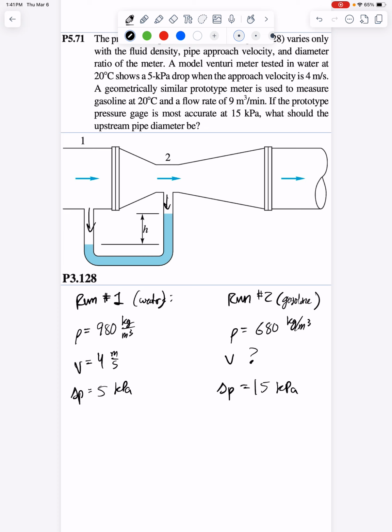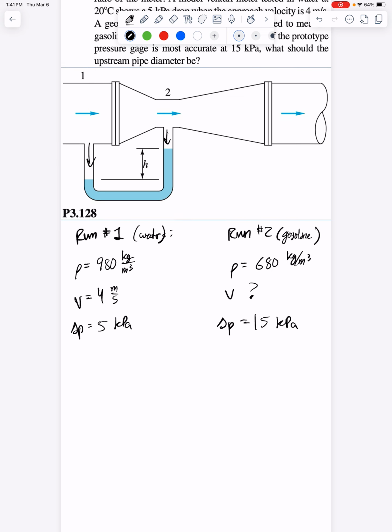First up, we want to match the flow characteristics between both cases in order to obtain this v value, because we want to make sure that the velocity is comparable to the other case. To make this comparison, there will be some kind of non-dimensional analysis, and the resulting non-dimensional term, or pi group, is pi equal to delta p, the pressure difference, divided by rho v squared. What you have here is a form of static pressure. And down here, this is dynamic pressure.